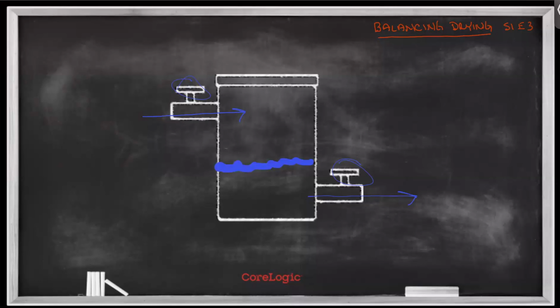If the water line in this bucket is increasing over time, right? So this is going up, then obviously the water is flowing in at a greater rate than it is flowing out, right? So that would mean that more water is being added, less is being removed. The net impact is that we're seeing an increase over time. And again, the way to drive this home in the analogy, the way we would evaluate this is by looking at the grains per pound within that affected area, right? If grains per pound are increasing, then that means that water is being added to the air in that environment faster than it's being removed.